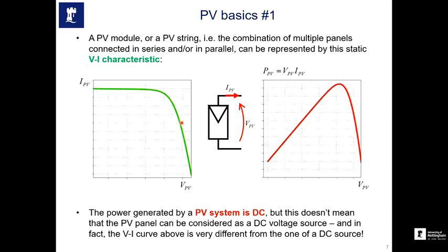So at that point, you have, of course, a current and voltage relationship. But in a normal DC power supply, the power supplies that you used in the lab, you remember the load actually controls the current, right? Depending on what load you connect with the power supply, whether after a DC-DC converter or something, if the load needs more current, you will get more current out of the power supply.